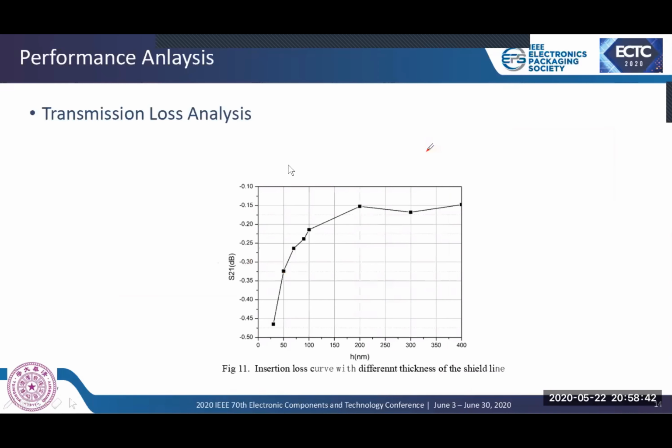We add a shield line to improve the performance. But how thick of a shield line is effective? To answer this question, we set a variable of thickness to analyze. The variable was also mentioned in section 2 above. In Figure 11, the x-coordinate is the thickness, and the y-coordinate is the insertion loss.